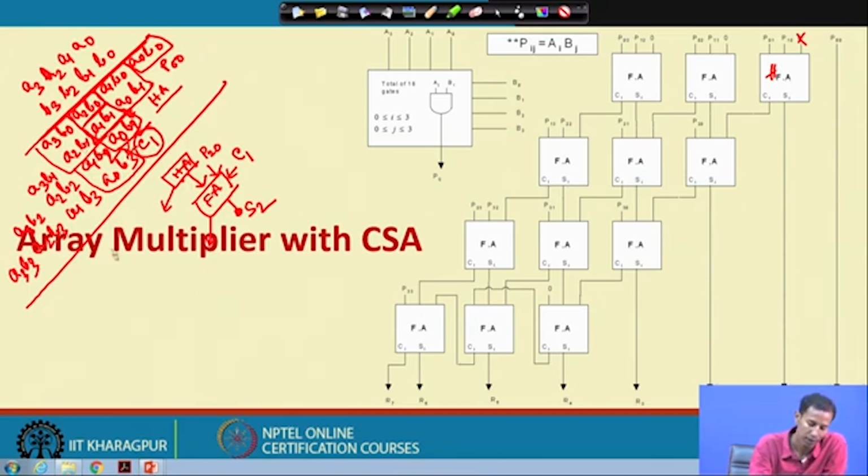So, for this particular case I need one full adder considering this P30 and here this P21, along with the carry of this. This is one full adder cell, and this will generate the carry. Okay.